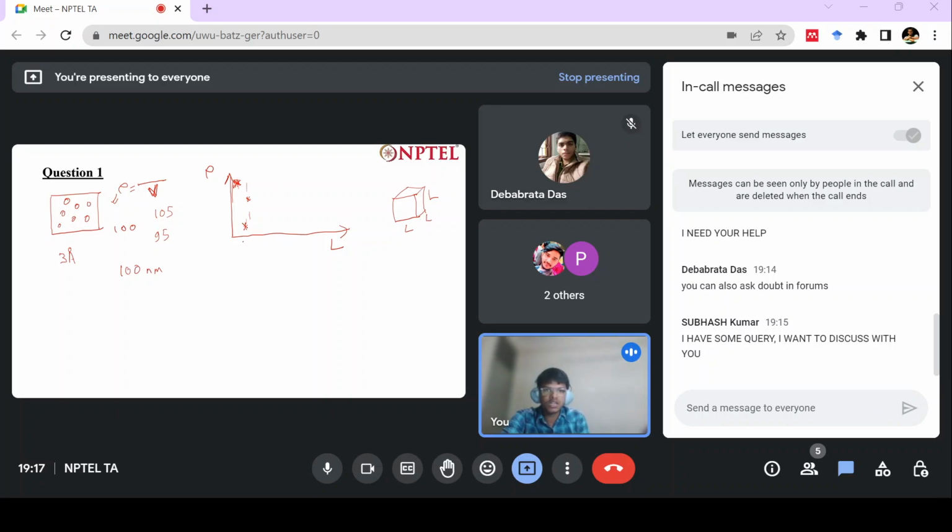But as soon as we start increasing our length scale, as soon as we start making our box larger and larger, we will get more and more molecules inside this box, and thus this density will slowly keep on converging to a value. After a certain threshold, this will gain a steady value. So what is this? This is like the mean density, time average density, and this will get a stable value, and this is the region where we can actually consider my fluid as a continuous medium.